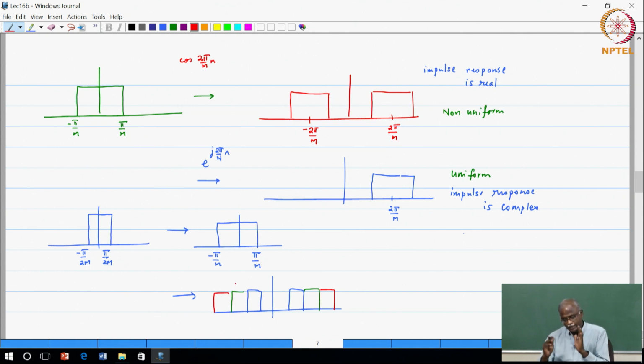The colors show the pairs. Okay. So k equal to 0 is your basic filter, that came from a different set. All of the derived filters or the modulated filters came from a prototype filter which was half the bandwidth, and of course you would satisfy this condition. Again, there are applications where this type is used, however our focus is not this. We want to have uniform, but we do not mind having complex responses.